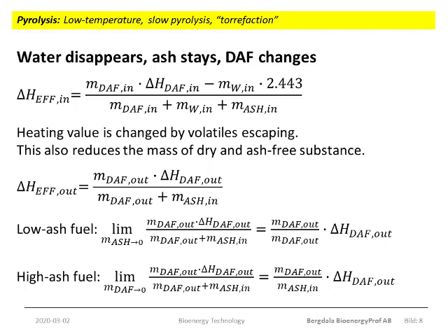So the heating value of the dry and ash-free substance is increased, but at the same time there is a mass loss from the dry and ash-free substance. So the total amount of energy in the solid material will decrease. The householding of this energy loss is typically managed so that the heat needed for the pyrolysis process is supplied by the combustion of the light hydrocarbon gas mix mentioned earlier.